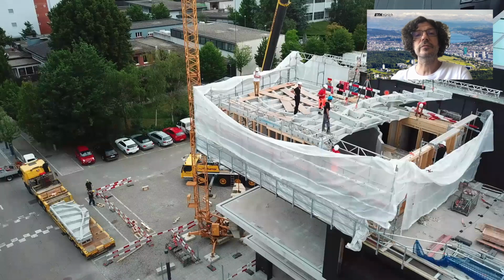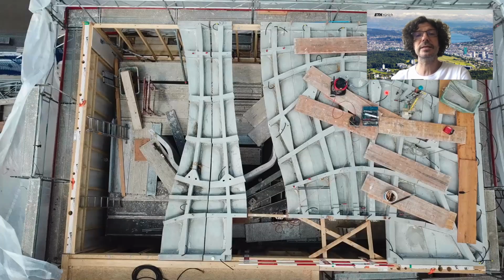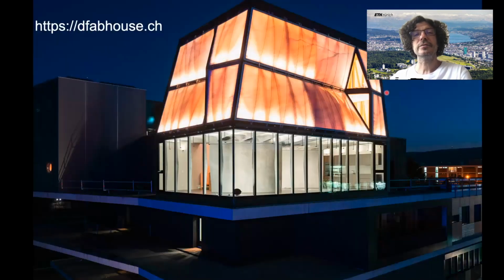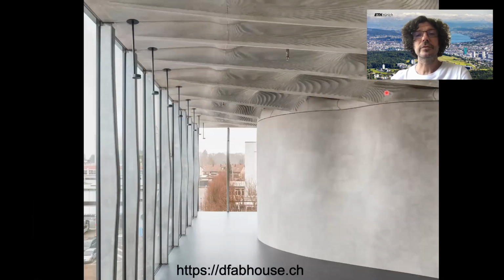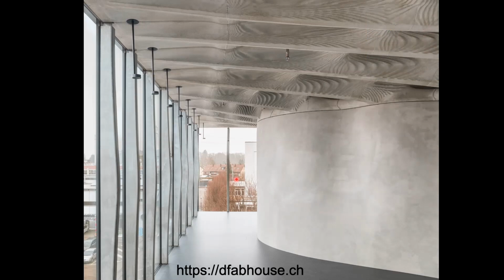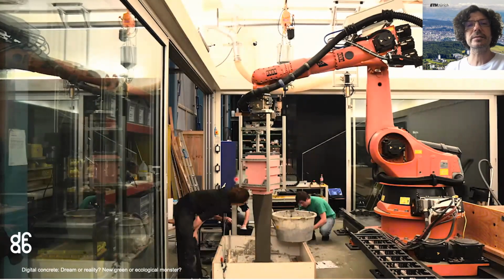These are elements of a post-tensioned slab for the DFAB house at EMPA, of which you see a picture here, and for which I invite you to visit the website. Inside the first floor of this house, there are a variety of concrete objects that have been produced with different digital fabrication processes. Here you have this roof where the mold was produced by powder bed printing. Here is a so-called mesh mold where a robot has created a rebar cage out of steel that is then filled with concrete. And here we have columns, mullions actually, holding the windows, and these are produced by so-called smart dynamic casting.